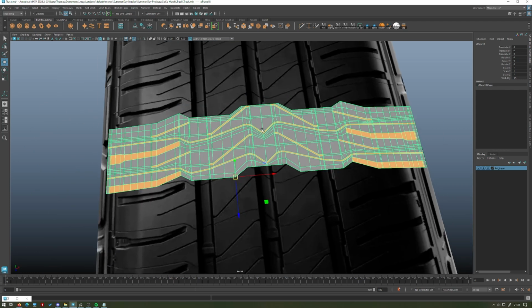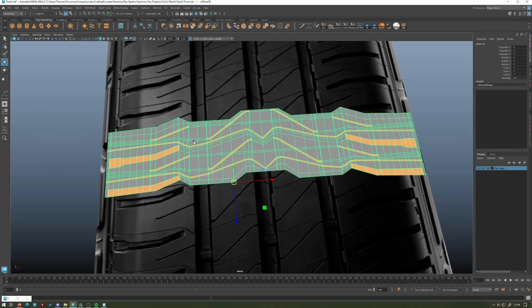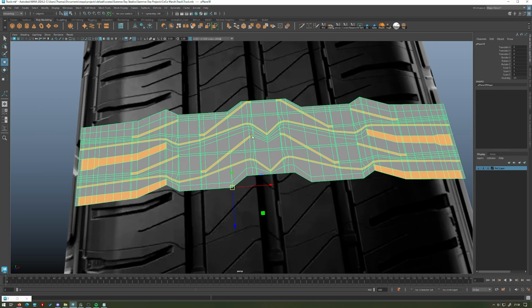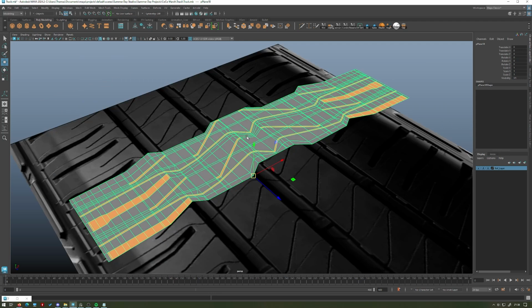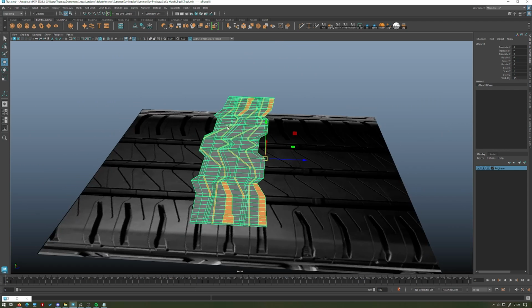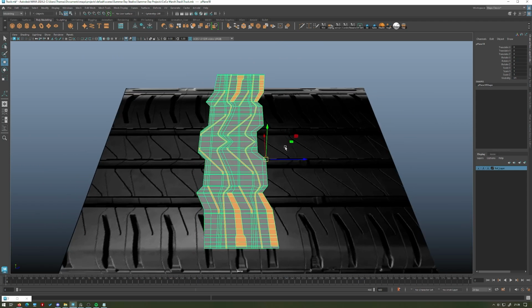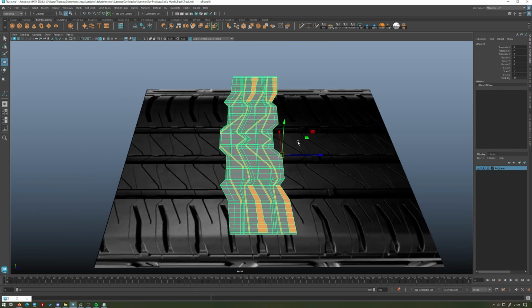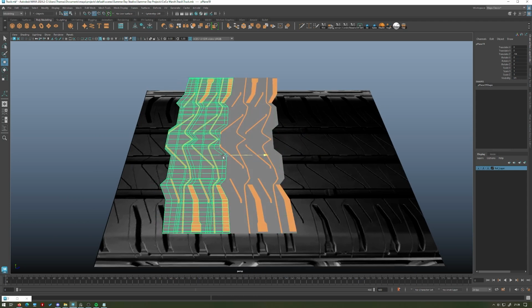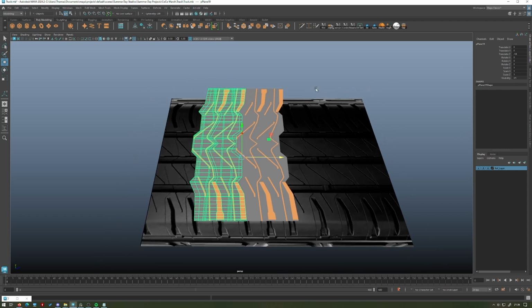And at this stage, guys, it is very, very important that you have this separate color in for the tread, because essentially we're going to use that material as a way to select everything before we extrude it. So before we do anything, make sure you have that in there before you duplicate this out. Once you're ready, I'm going to press Ctrl D, and I'm going to drag that until it snaps just to the edge, which for us happens to be -14, like we did before.